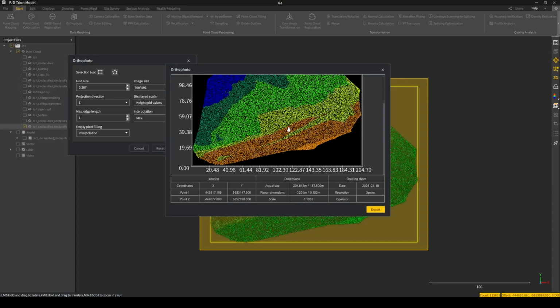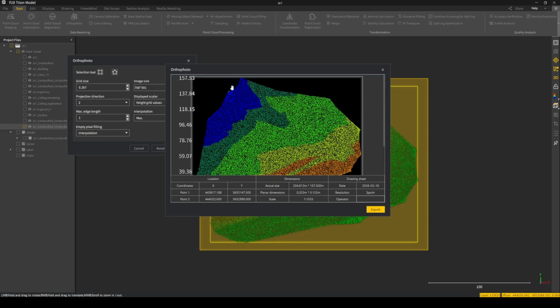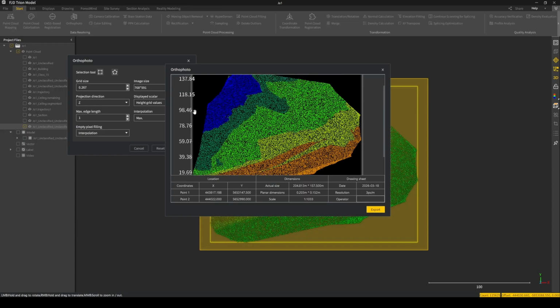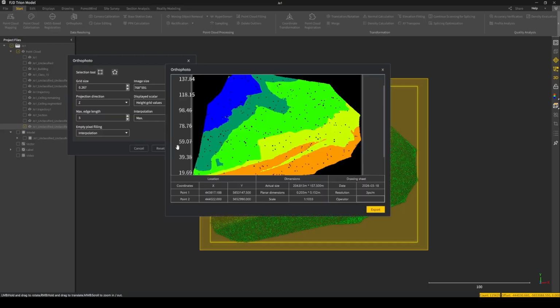And as you can see here, we have a lot of gaps in between pixels. So those dark areas inside here are gaps without any elevation information. So your terrain model will also have gaps if you use this for the next steps inside QGIS. And in order to remove those gaps, we need to adjust the edge length. For instance, we can play with those parameters here with this number. We can hit preview. You see there are fewer gaps now.